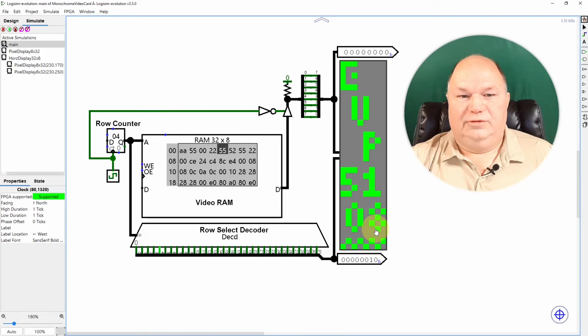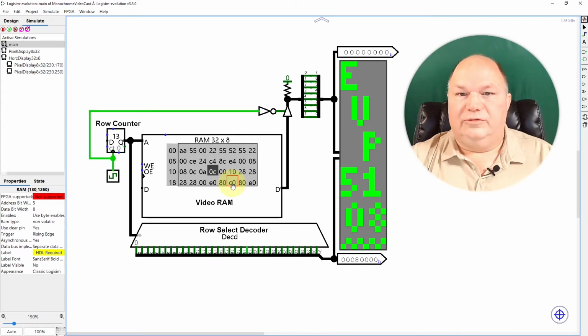EUP5108. Except that the E is just a little off. And that E, this line here in the E, is this byte in RAM. So if we change that to C0, we get our correct image. Now, of course, we don't have a way of manipulating RAM like that when the system is running. What we need to do is connect up the write enable and the data lines, and then that way we'll be able to change the RAM from the processor.